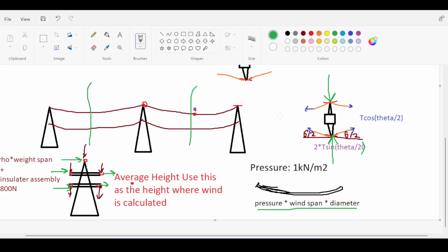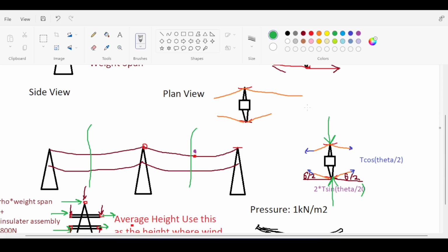So, well, there is a lot more than I thought about the cables, right? That's not all, because you have something called the failure containment load, and you have something called the snow load. Now, for the snow loads, truth be told, I live in a region where there is no snow load, so I would not be the best to talk about snow loads in that regard. However, you can calculate the snow loads and add them as a separate case for the loads on the conductor. In my case, I will ignore it because I don't have any snow loads here, and I like to be 100% sure of information when I give it. So anyway, there is no snow load here, but the last thing is something called the failure containment load.